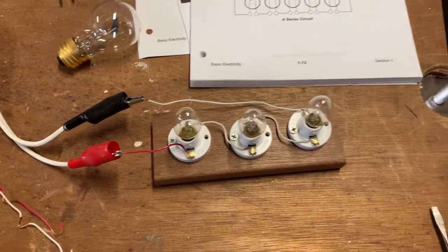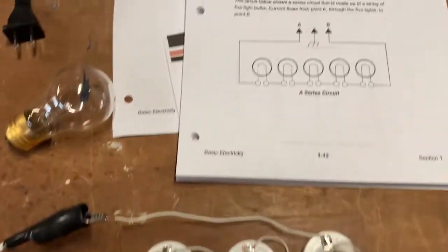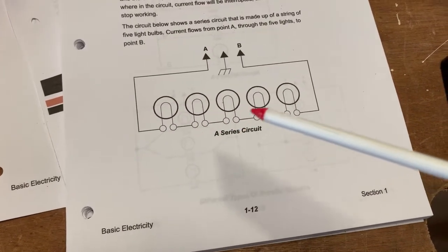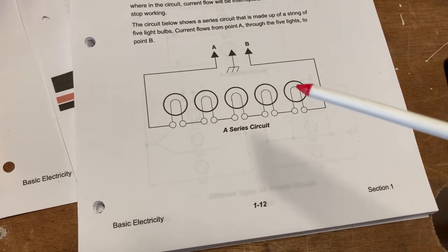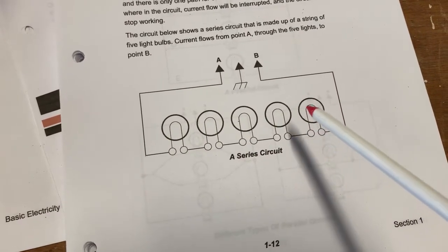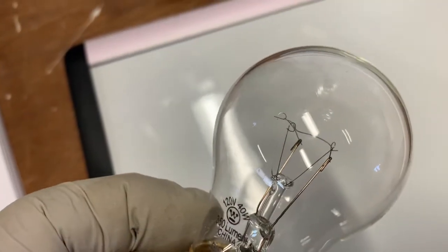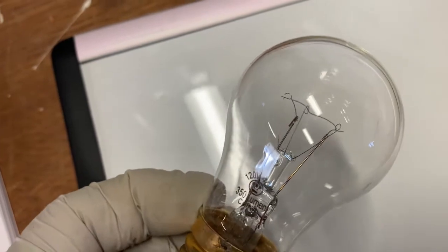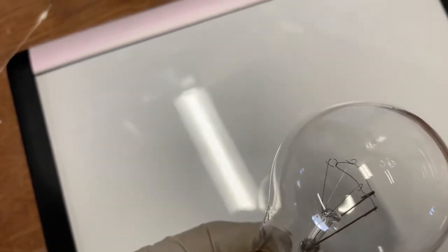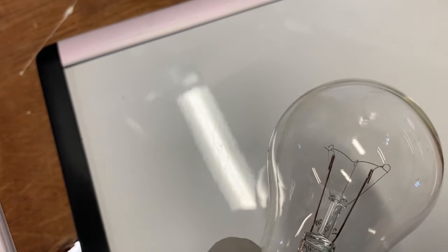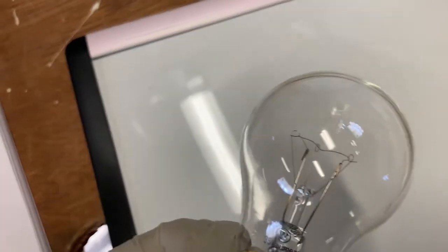And another thing about series circuits is that you'll see, because they depend on each other to continue the flow of electricity, if you have a bad filament in a light bulb, and that's what this wire inside the circle indicates, is the filament. That's a light bulb. And if you can see inside that light bulb, you see there's really just the two main wire connections coming in, and they go to a real fine wire that's looped around. And because it's so fine, it has a lot of resistance, and that's what makes it glow. But it is really just a wire.